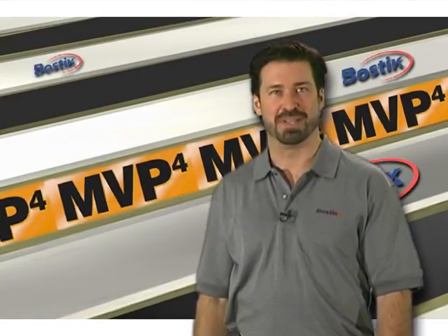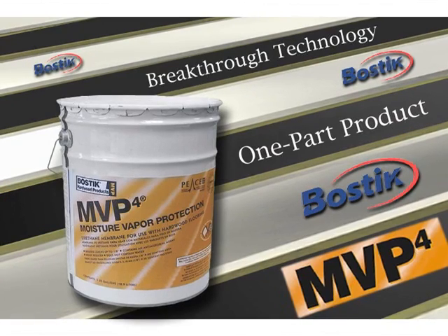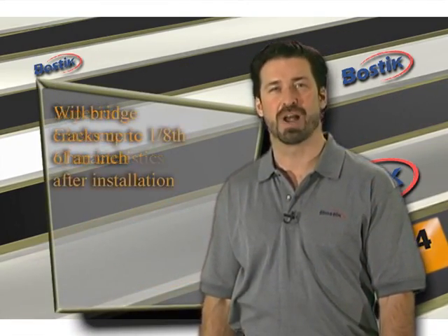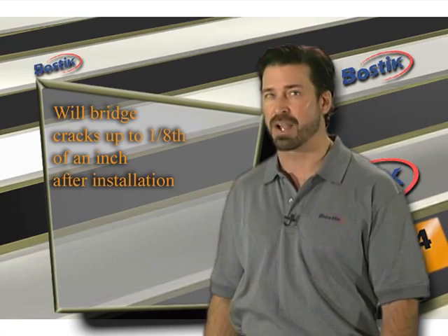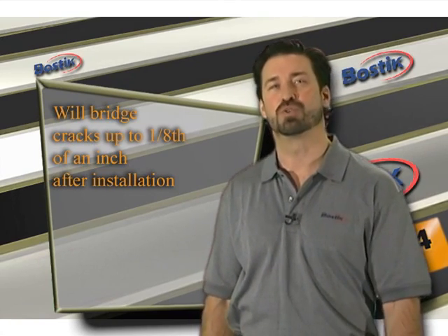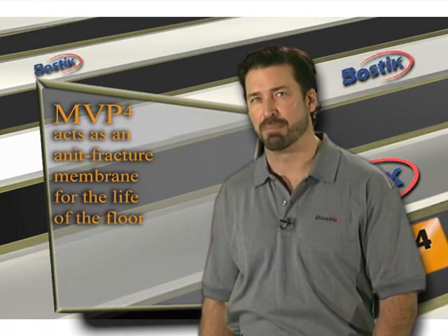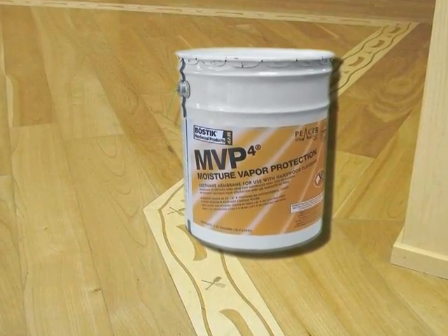Installation of Bostik's MVP is quick, easy, and extremely user-friendly. MVP is a one-part product created with breakthrough technology to dramatically reduce the rate of moisture vapor transmission from a subfloor. With its superior elastomeric characteristics, it will bridge cracks up to 1/8 of an inch that occur in the substrate after installation, whether the crack is a designed crack, such as a control joint, or uncontrolled cracking. The integrity of MVP is assured, as it acts like an anti-fracture membrane throughout the life of the floor. Applying MVP4 is as simple as opening the pail and troweling the product.